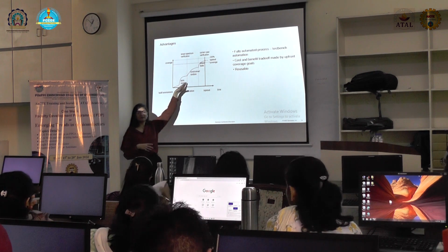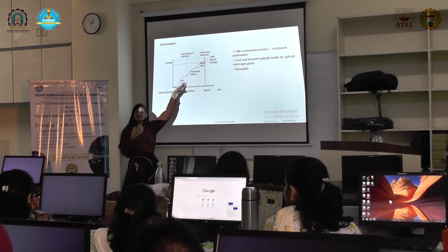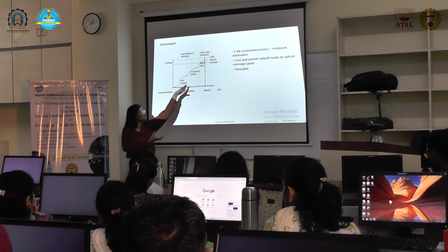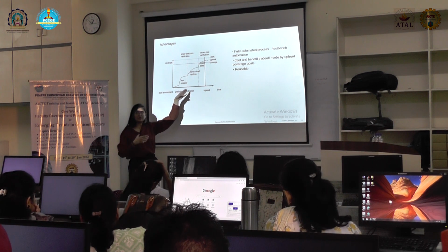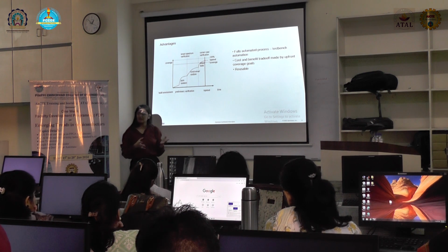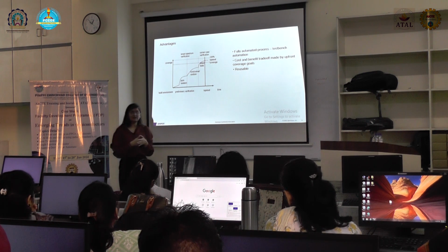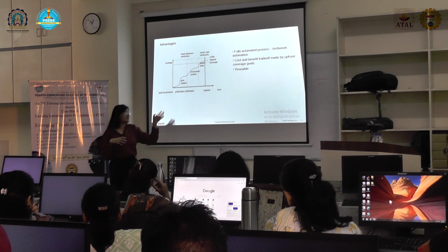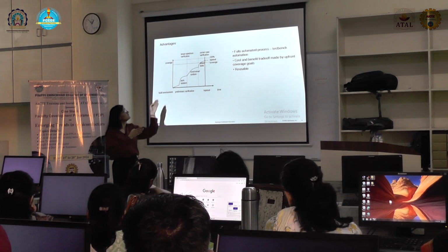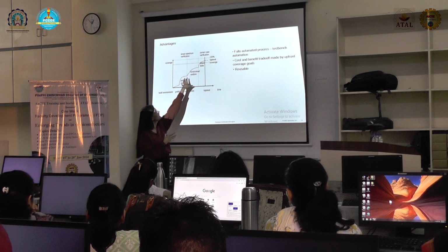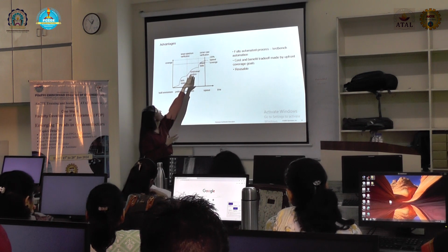Then we need to limit the randomization. As I mentioned, constraints need to be added to limit illegal stimulus or stimulus which is not required. So we add constraints in order to dilute the randomization that was being created. Unnecessary randomization and coverage that was not required, we remove by adding constraints and we limit that. It will again improve the tape-out cycle for the coverage significantly.